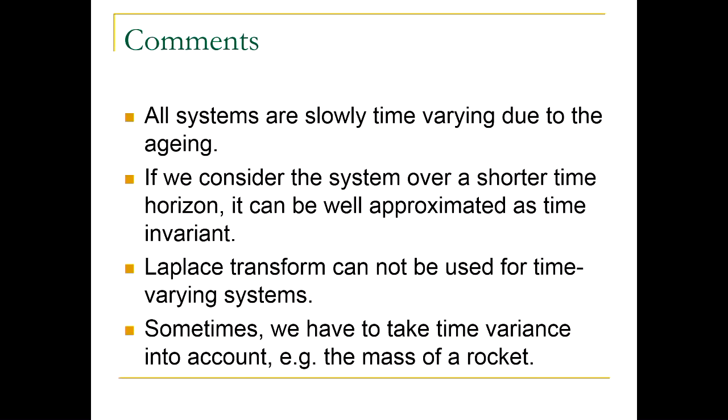Know that the Laplace transform cannot be used for time varying systems. So if we wanted to account for time variation, we wouldn't be able to use one of the most important tools in this subject. So we have to be happy with this approximation of true systems in order to use a lot of tools. Sometimes you need to take time variance into account.